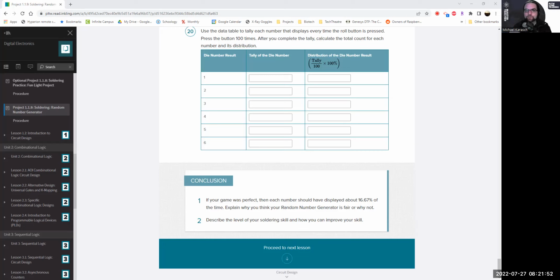But for you guys in your classrooms, solder with lead in it has a much lower melting point, much easier for kids to work with. Now, lead is a bad thing for you to have in your body. But misconceptions: lead does not vaporize. It doesn't go into the air at the temperatures that we're using. So if anybody tells you that kids are breathing in lead, no, they're not. That doesn't happen. It does get on their hands.